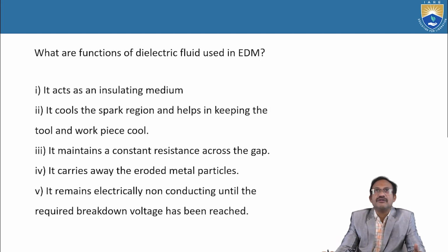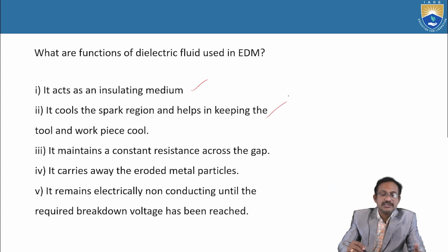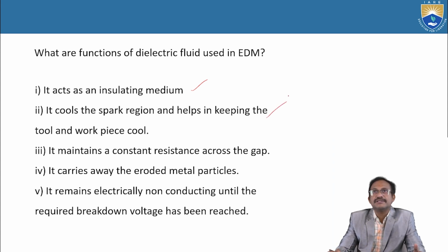What are the functions of dielectric fluid used in EDM? First, it acts as an insulating medium. Second, it cools the spark region and helps in keeping the tool and workpiece cool. Third, it maintains a constant resistance across the gap.